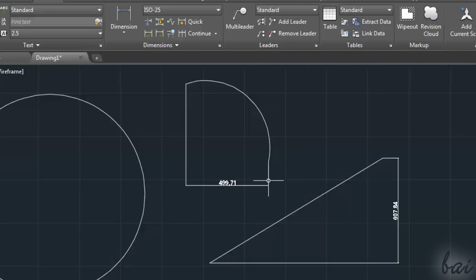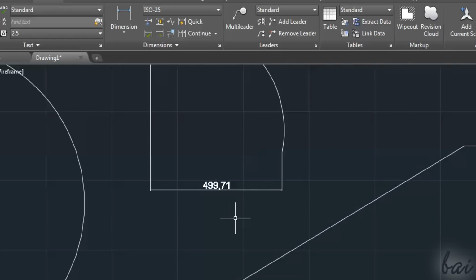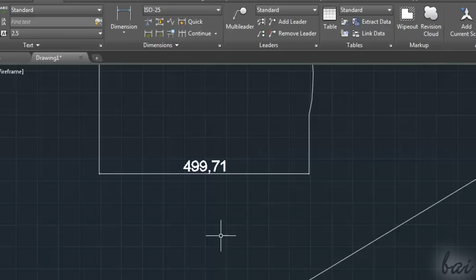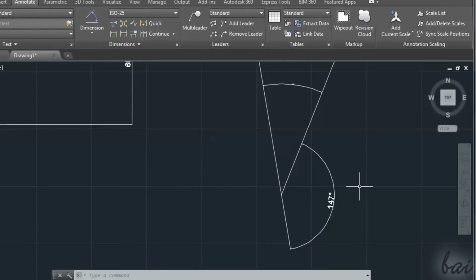You just have to keep in mind that AutoCAD uses, by default, the meter scale for lengths, so convert to meters if you have lengths in feet. Also remember that the comma separates decimal units, not the dot. Angles do have a measurement unit instead, which are the degrees.